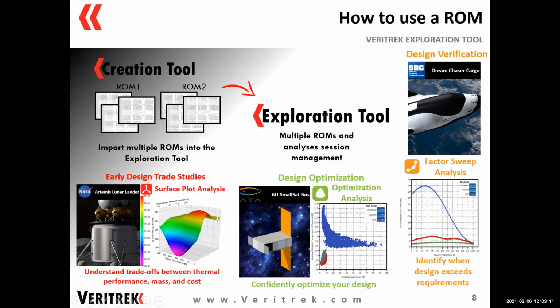And so they used Veritrek's surface plot analysis that we took a look at a few slides ago to really understand how changes in their inputs affect that heat load going into the cryo tank. So they walked away with a much better understanding of how sensitive that heat load is to variations in the environmental parameters.